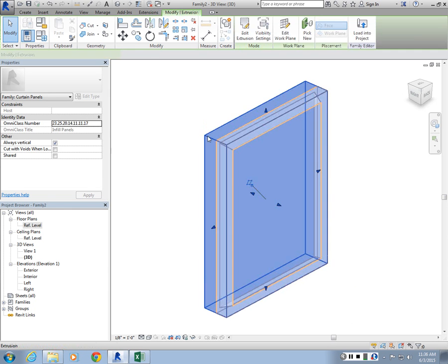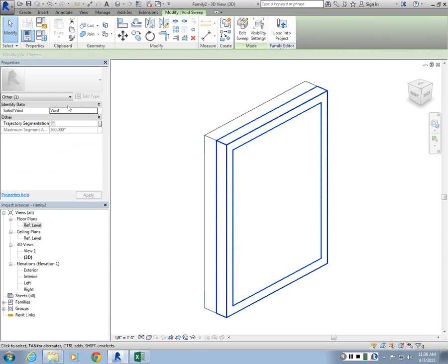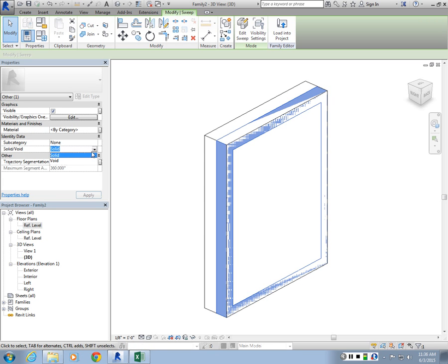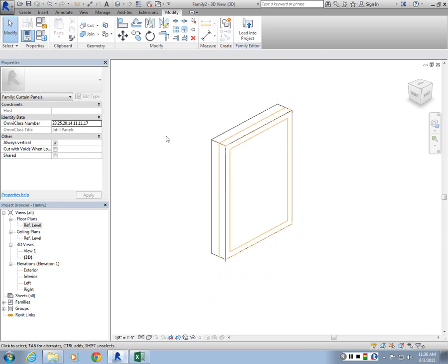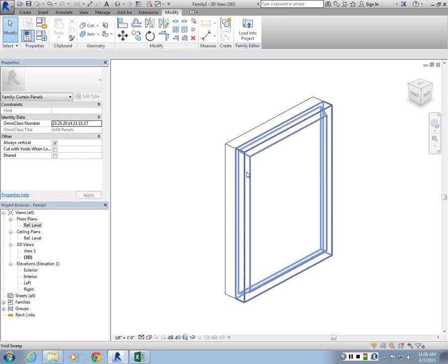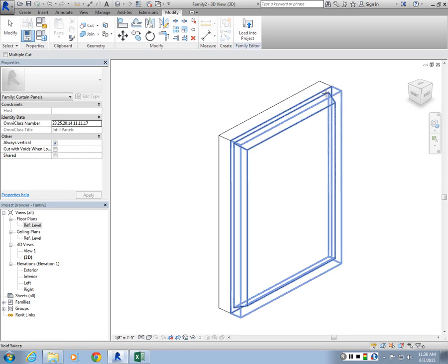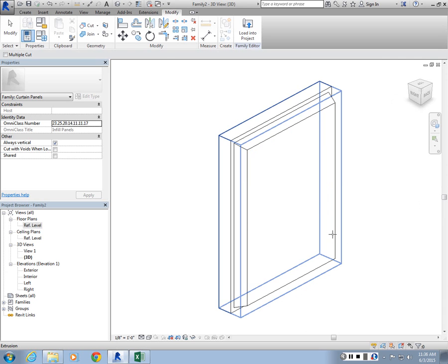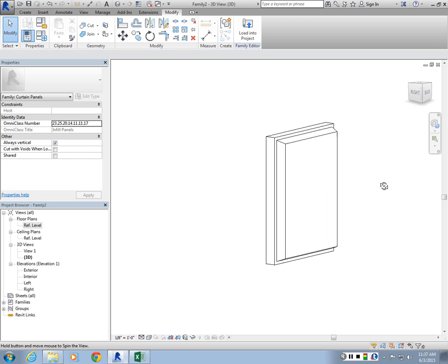Now I basically have a 3D extrusion and a 3D void extrusion as well. And I went in and chose the solid void configuration of this extrusion to be void, so that we won't see it as an object in the family, and it becomes orange. But in the family, sometimes the void geometry is not directly taken out from the solid, so you need to define a cut. So I go to cut geometry, choose the solid object first, then choose the void object to define that operation. Okay? So I'm making it into a frame basically.